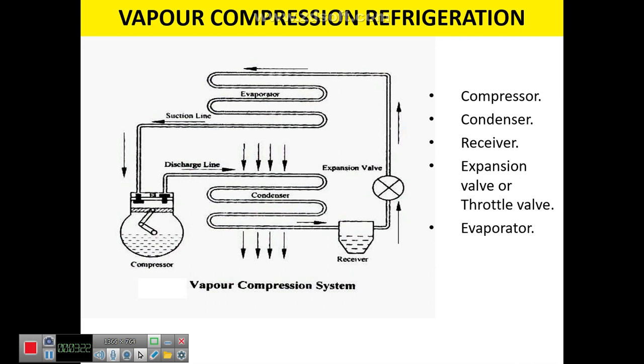So we have to remove the heat first. By passing through the condenser, the atmospheric air having contact with the condenser pipeline, the pressure and temperature of the refrigerant are going to be reduced. Some portion of the gas turns to liquid, which is collected in the receiver. So the output of the condenser is a low temperature, high pressure refrigerant. Here we have to get low pressure and low temperature, so now we have to reduce the pressure level.